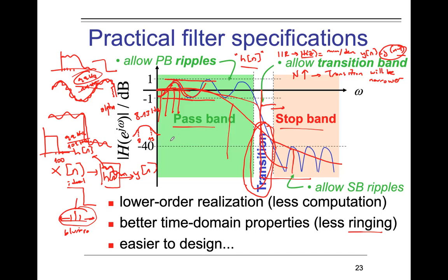If I have such a very sharp filter, whose cutoff frequencies are again 13 and 8, what is the attenuation level for, let's say, 6 hertz? 0, right? Almost 0. What is the attenuation level for 14? It is almost 0. So I don't allow other bands to interfere with my power calculations.